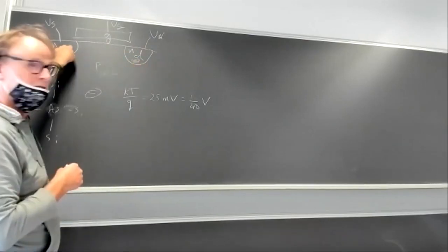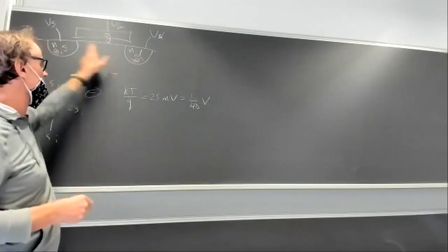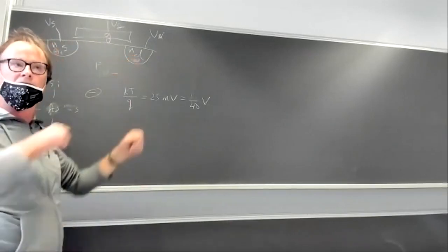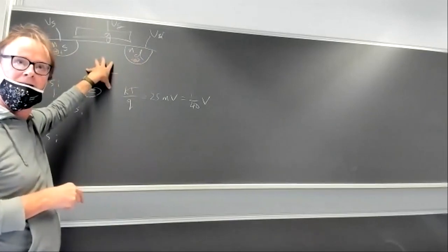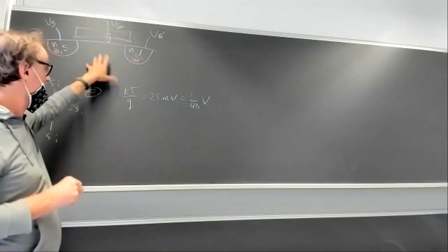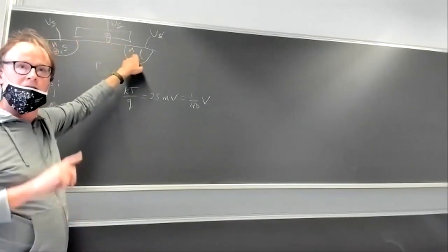They get pulled in from the source for this N FET. Why is it called an N FET? Because the source and drain are N type. And that's what flows through the transistor. The bulk is opposite, it's P. It has a lot of holes, but what flows through this N type transistor are electrons, not holes.